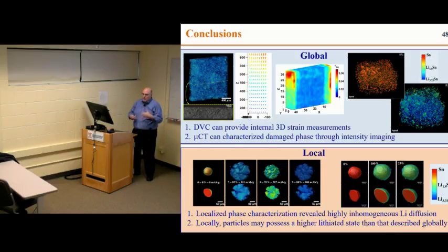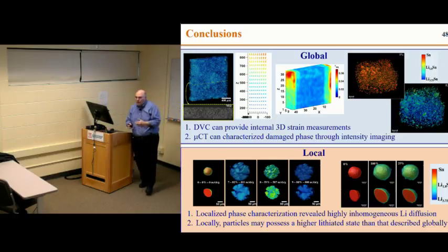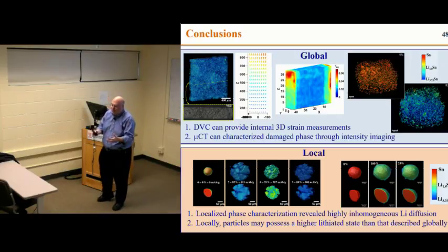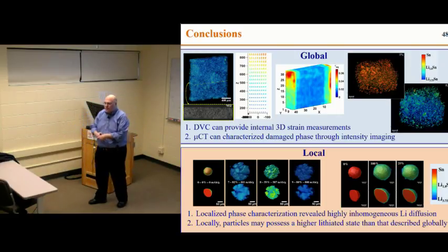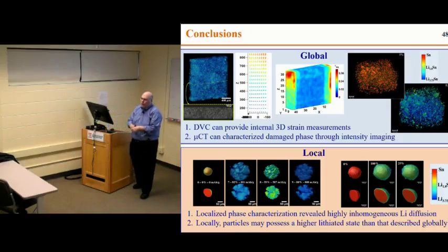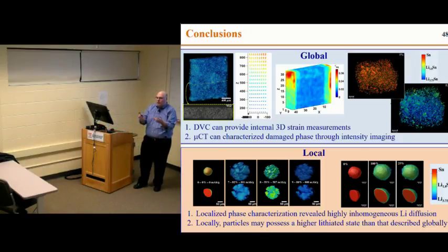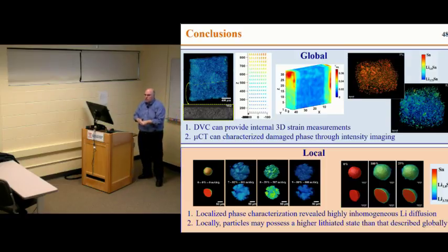The bigger problem is, in terms of sample sizes, do you have enough energy of the radiation to penetrate through, right, and get a reasonable image? Certainly the machine that we're using at Beckman wouldn't be able to do that. So you would need a higher intensity machine, right? And you want to be able to penetrate through something that's large enough to be an RVE, to be representative. Again, it depends on what you're trying to do. If you're trying to look at the interaction of a single aggregate with the surrounding matrix, you could probably do a geometry like this. That might work. If you're trying to do an actual 60, 70, 80% volume fraction composite and want to get a representative set of properties, then yeah, you would need a much larger machine than what we would have here.